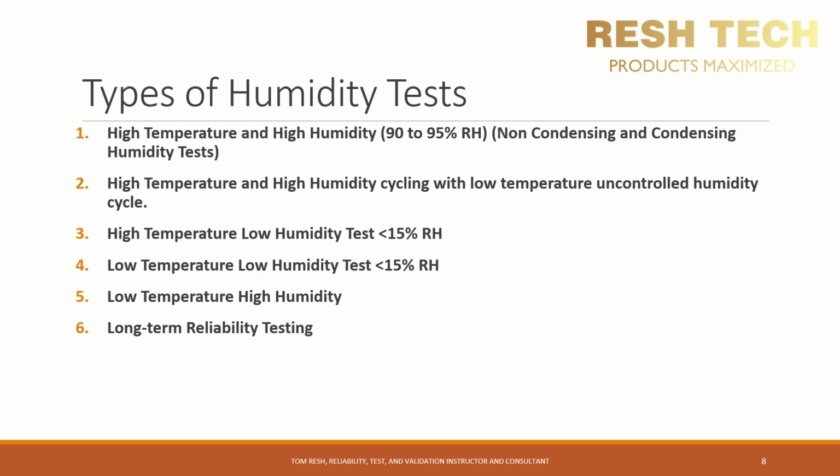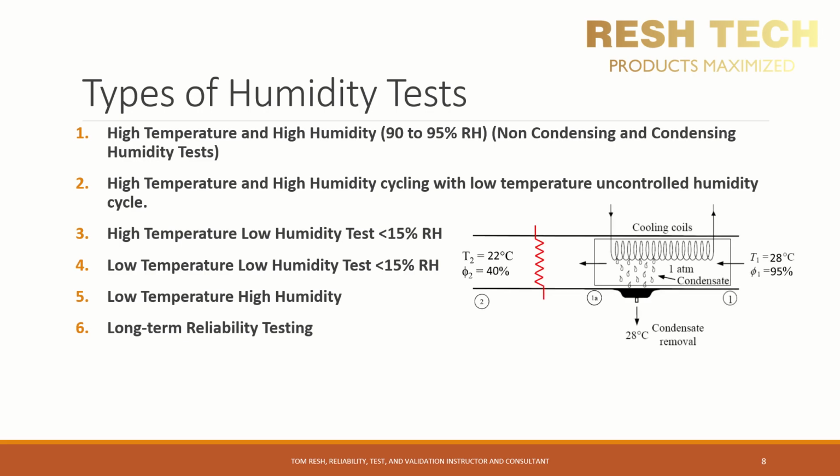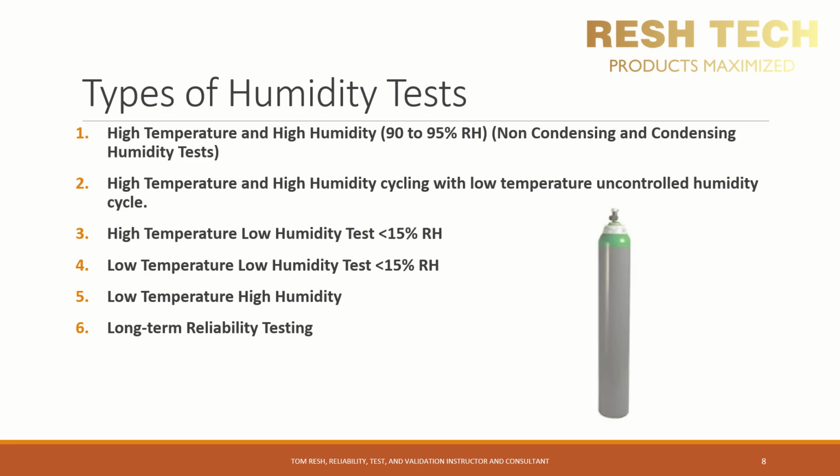This testing can be accomplished with a humidity chamber that has a dehumidification coil, which is basically a small evaporator that captures and condenses moisture from the air. Additionally, you can accomplish this as well with a pure compressed air source to reduce the relative humidity in the chamber to an even lower dew point. Likewise, a low temperature and low humidity test simulates colder, drier climates that occur in the winter, which can also be used to assess resistance of the system to static electricity and cold temperature environments.